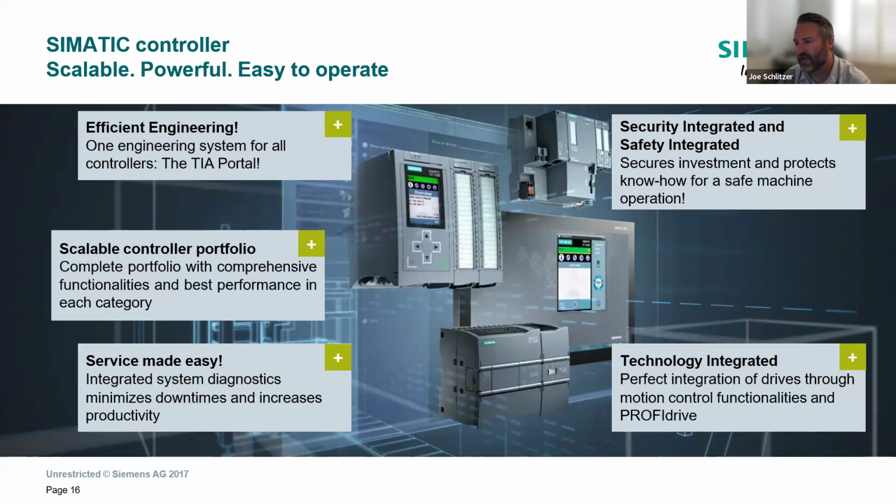A lot of the existing security functions that were turned off by default are now turned on by default, and they've added a lot more functionality when it comes to safety. The programming for the S7-1200 to 1500 is very scalable. For the most part, you could bring any programming blocks that you have done in the 1200 to the 1500. There's some small limitations there, but if you ever had a small project and you started off with a 1200, getting it over to a 1500 is pretty simple.